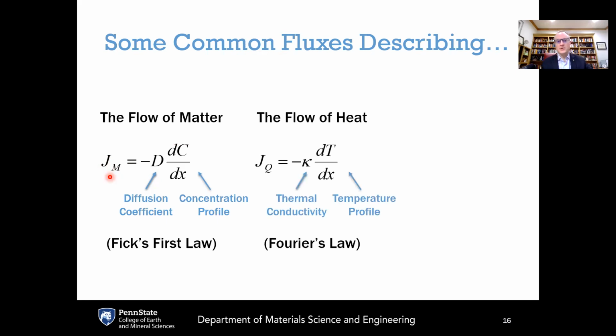Another common flux equation is Fourier's law. In this case, this is the flux of heat. The thermodynamic driving force is a temperature profile. The kinetic parameter is the thermal conductivity. So the higher the thermal conductivity of the material, the faster the heat will be transferred.